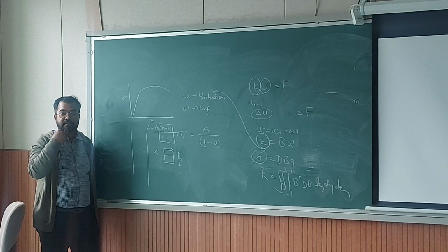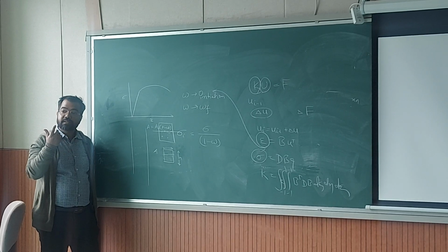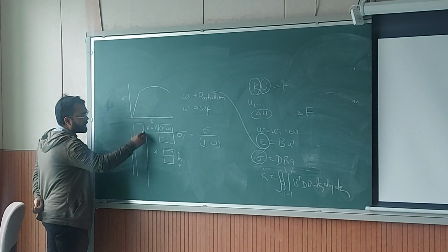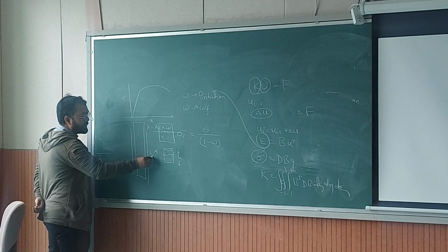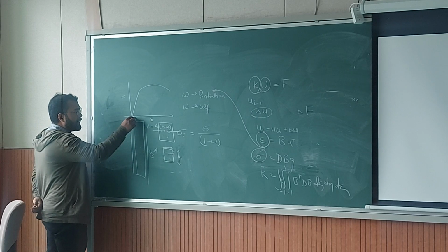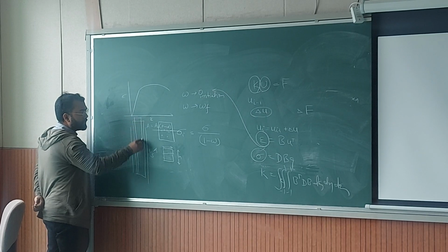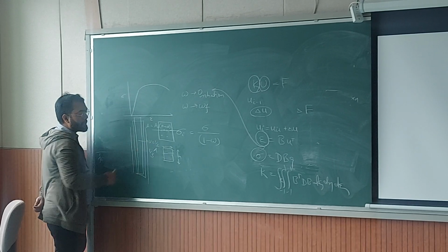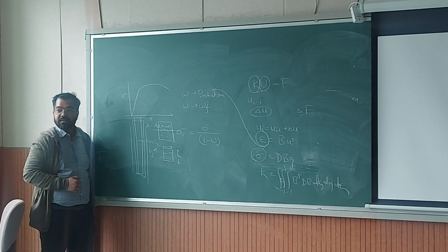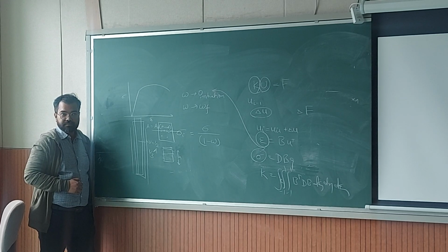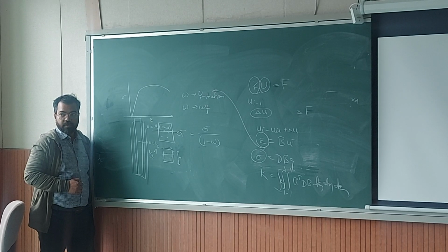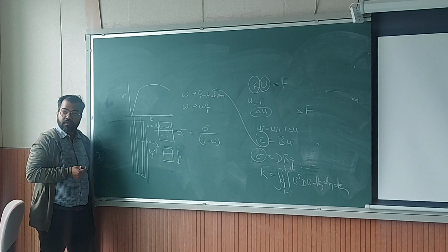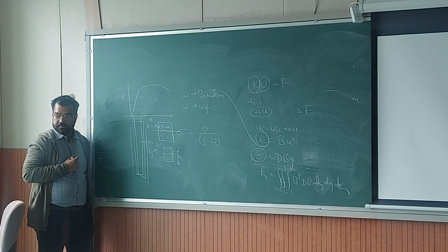There will be elastic strain, there will be plastic strain, that's it. It will just get elongated. So this tensile sample will elongate with a Poisson's ratio of 1 by 3 initially, if that is that. And after that, it will elongate uniformly with a Poisson's ratio of 1 by 2. And it will always be uniform. Okay? So unless you create damage, only then you can simulate necking.